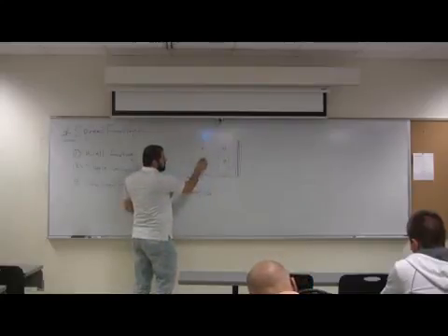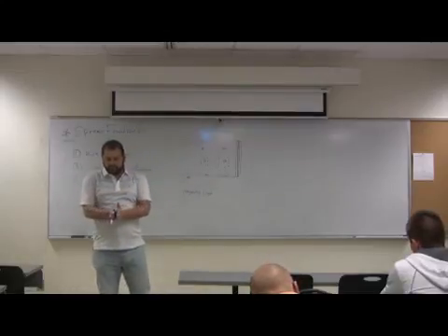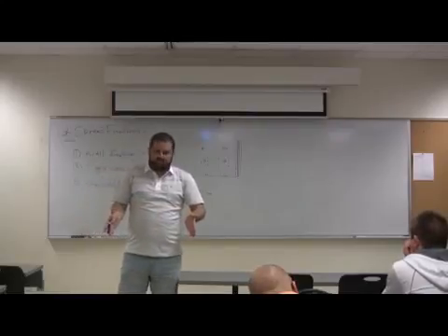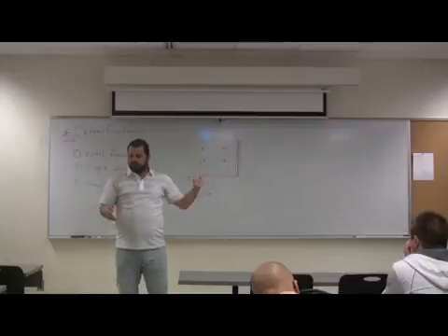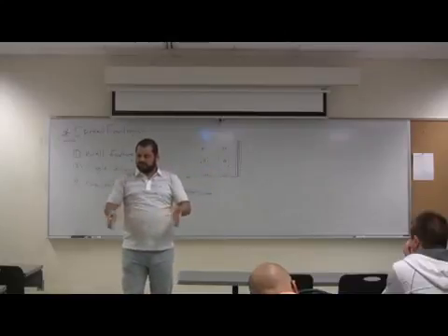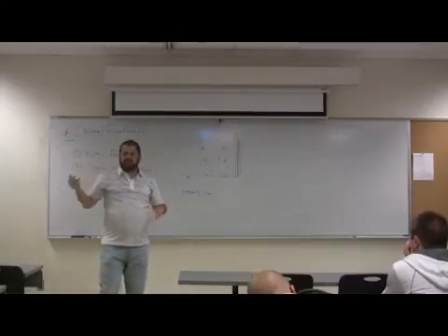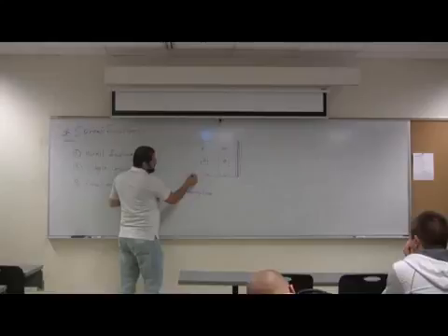For this one, you will have no problem doing a square footing. Sometimes you don't want a square footing because you are narrow with the width. You are fixed with the maximum width that you can go. Let's say you cannot go more than 6 foot. So your single column footing will be a rectangular footing, 6 by whatever you need. We're going to see how we calculate the required area. Sometimes we combine them, something like that.